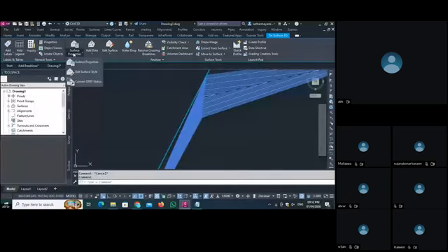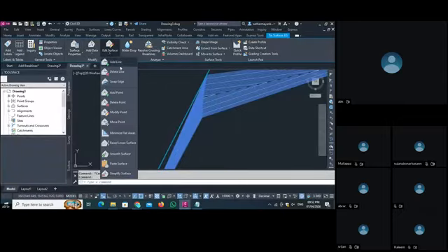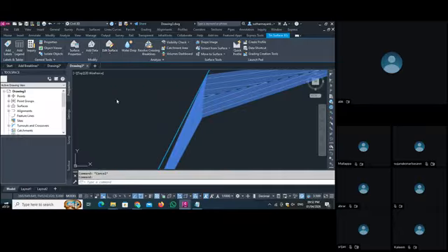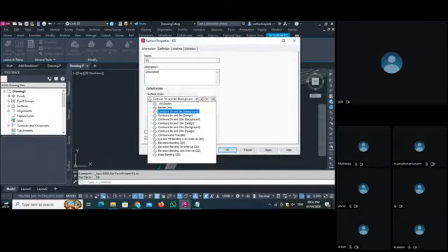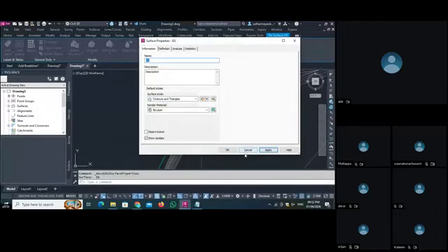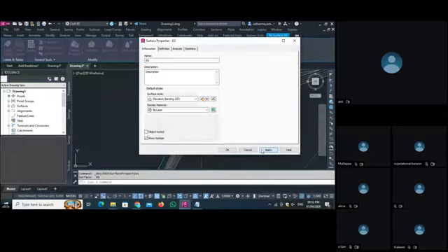For that, we select the contour and again go into edit surface. We can delete the points. For that, we have to change the style again. From the information tab, select your style as contour and triangle. Apply. You have to give the name of the contour, elevation. Apply.